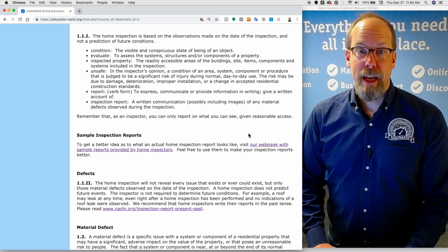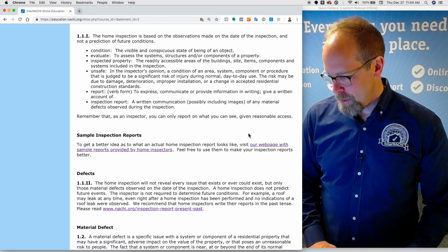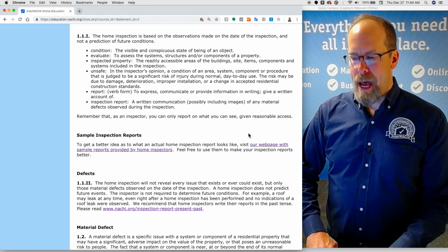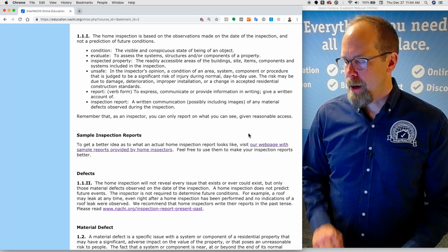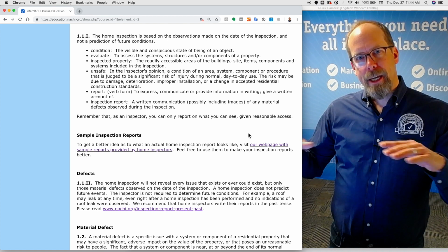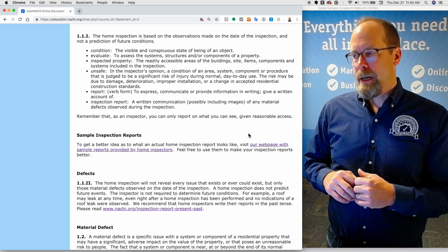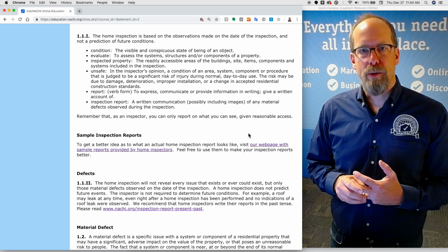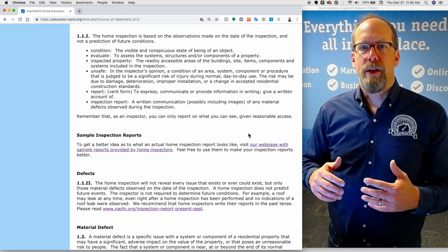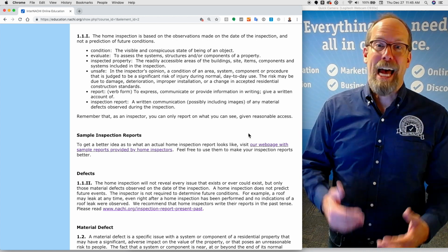You may come across an unsafe deck in your experience. I have had that in my occupation. Where the deck is attached to the house, it's called the ledger board, and there should be flashing properly installed at that ledger board. Well, there wasn't on this deck, and water got behind the ledger board and completely deteriorated the house structure to which this deck was attached.